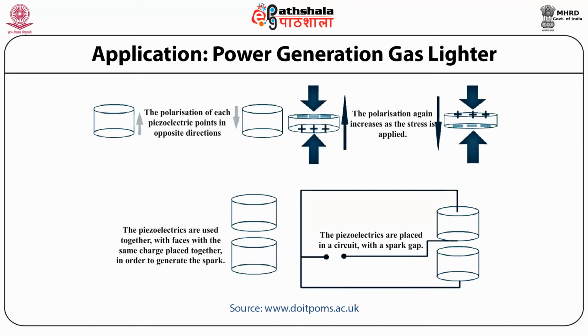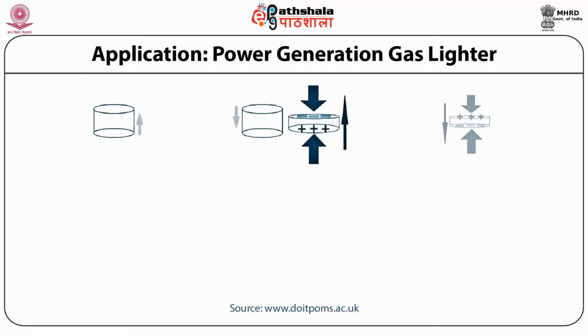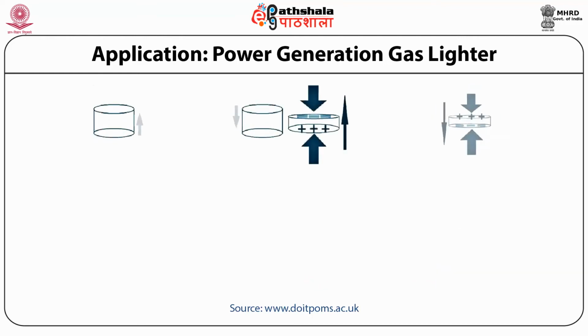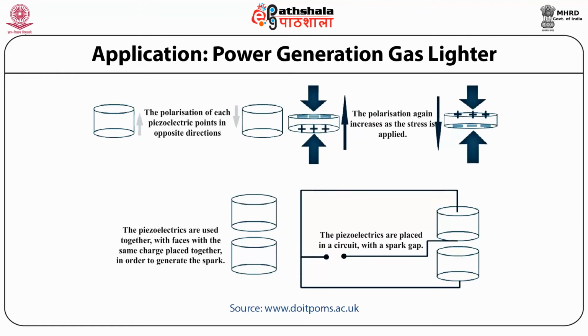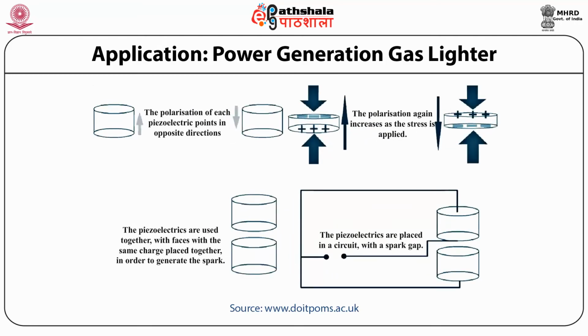The piezoelectric materials can ignite gases by generating a spark through an electric current. This requires two piezoelectrics with opposite polarization states which are brought close to each other. So those polarization vectors are in the opposite direction. That is, the faces containing similar charges are together.